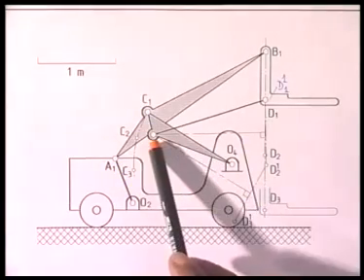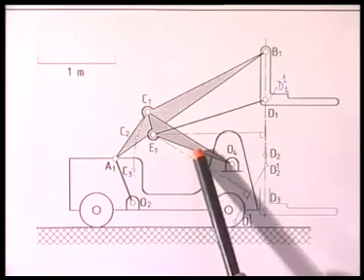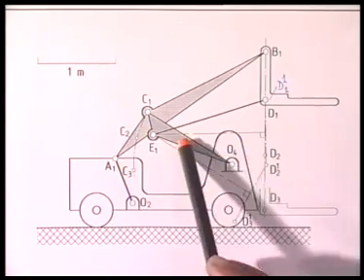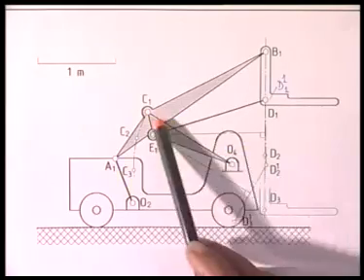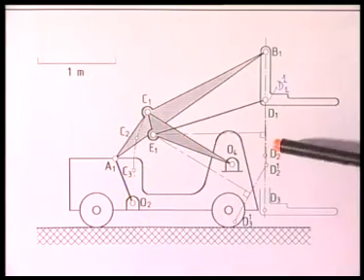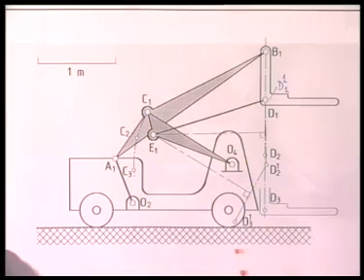To locate the position of E1, that is this revolute pair on link number 4, again I apply the method of inversion holding this link, that is link number 4, O4C, fixed at its first configuration and determine where is D21 and where is D31. To do this, we follow the same method of kinematic inversion.